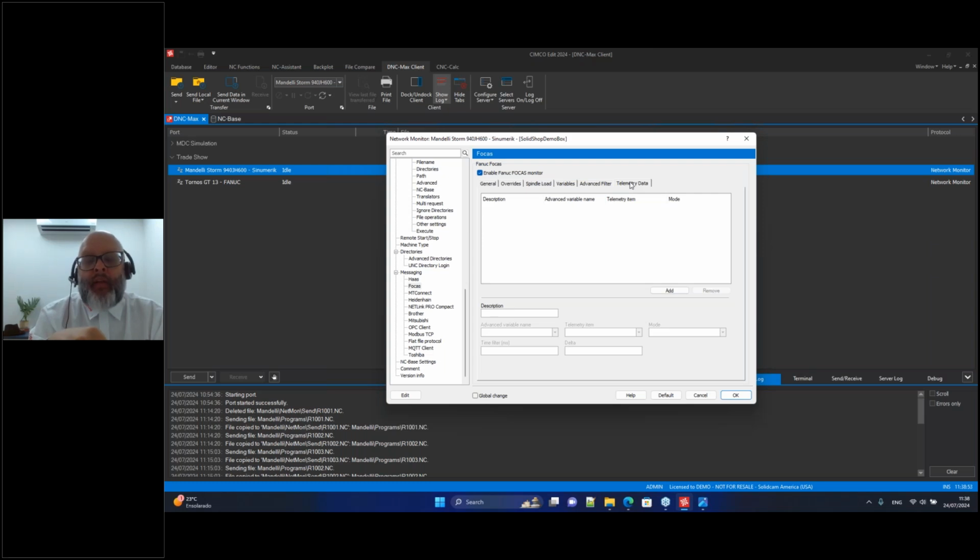Hey, I want to know if I have a gas interruption during the process or the operator reduces the speed of the welding, and what happened. When depositing the material, you need to control the speed. So they implemented this, and then they could say, hey, every time there is a reduction in the welding speed, we have a welding failure. And I can show you exactly when it happened and at what time, because I have telemetry enabled for that machine. So these are examples of scenarios that we can solve with this technology.